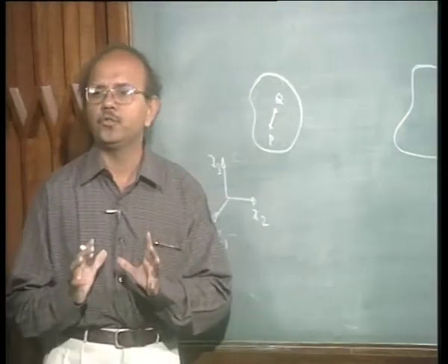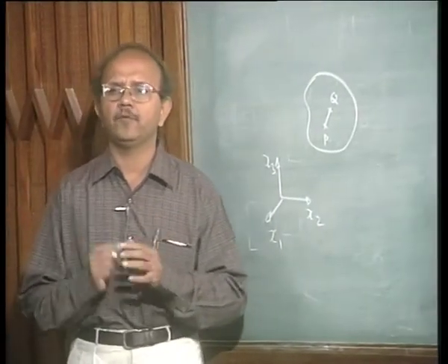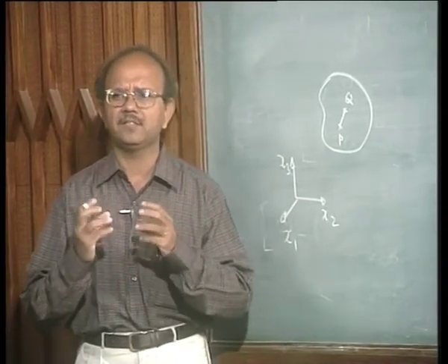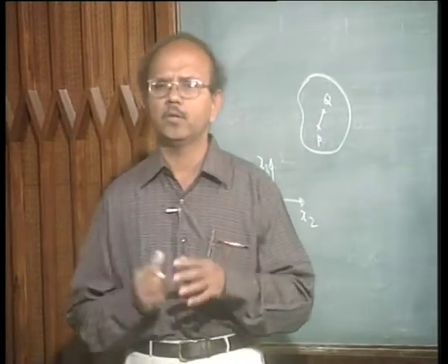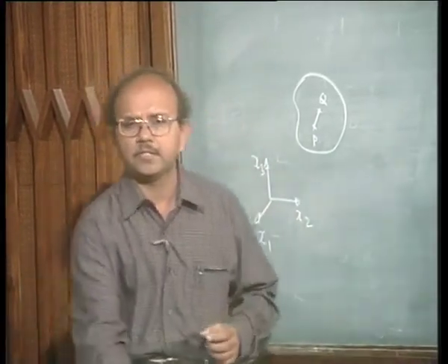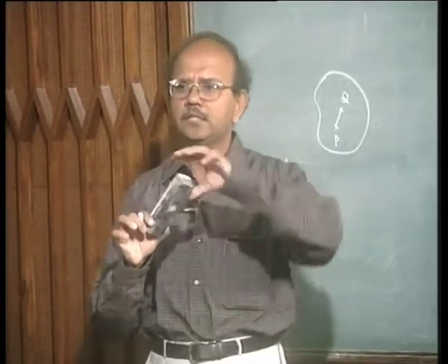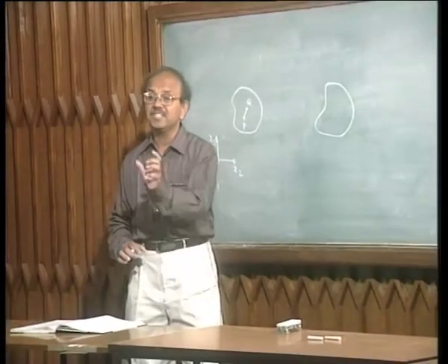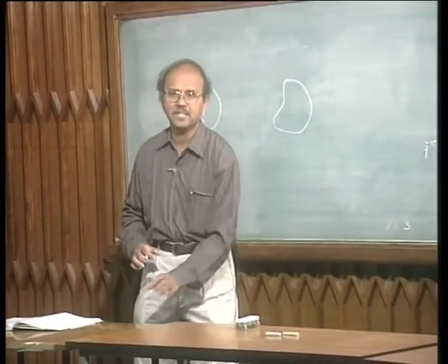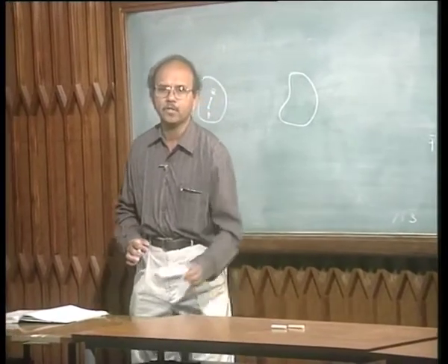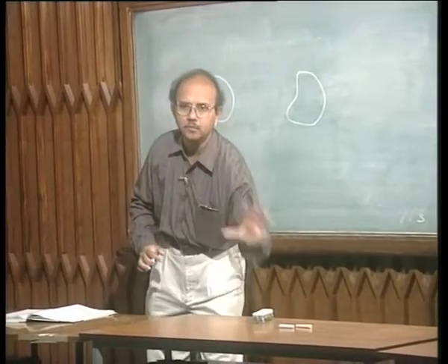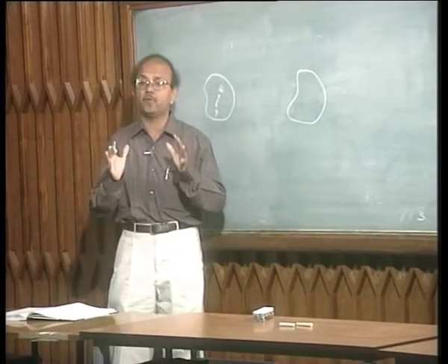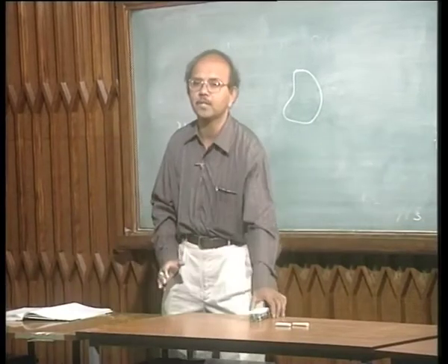There is usually a confusion between displacement and deformation. Okay. Now, let us try to understand a bit, and this is only a nicety, people may not follow it so closely. When this body, I have a duster for example, okay, this duster is just displaced and kept here. Okay? It is just displaced and kept here. Is there a strain in the duster? No, because this is a rigid body movement as it goes to this place. It is just a rigid body motion. As a rigid body, it is not deforming. As a rigid body, it moves from one place to the other place.